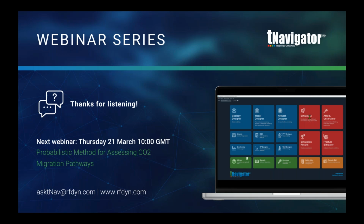Previously you would have had to write calculator statements, doing it manually via these equations, but now you can just click on the equation that you desire and output from there. And we've got volume shale equations available. So looking at your Larionov, Clavier, we've got a number of different variations that you can choose from.